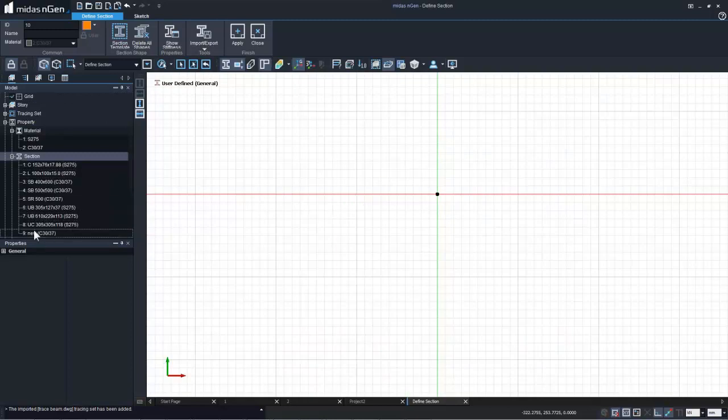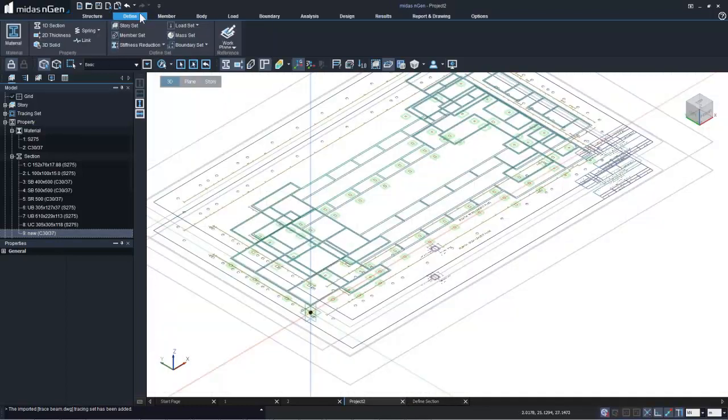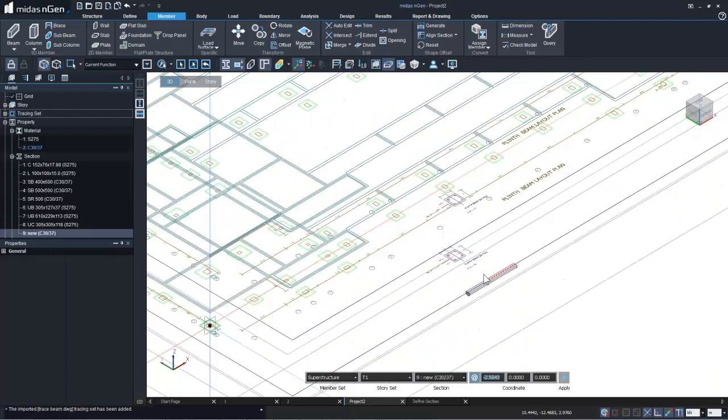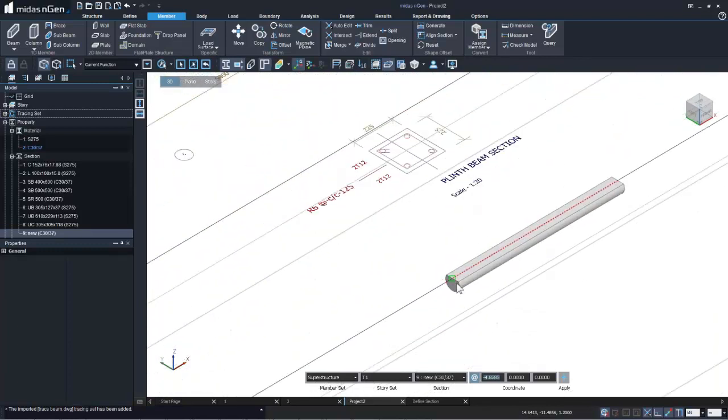And we can see that over here. So if you would like to use this, then you can go back, simply say a beam you want to create. Alright, here we have our command at the bottom. So we can select this new section that we have just defined, and for now in sample, click on 2 points. Okay, so as you can see over here, our irregular shaped beam has been automatically, very easily defined over here.